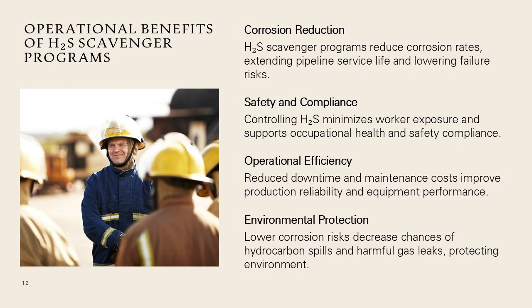Implementing H₂S scavenger programs offers wide-ranging operational benefits across oil and gas infrastructure. By reducing dissolved H₂S levels, operators can significantly lower corrosion rates, thus extending pipeline service life and reducing the likelihood of failures. Improved integrity management leads to reduced unplanned downtime, lower maintenance spending, and enhanced production reliability. Safety benefits are considerable, since controlling H₂S minimizes worker exposure risks and supports compliance with occupational health regulations.